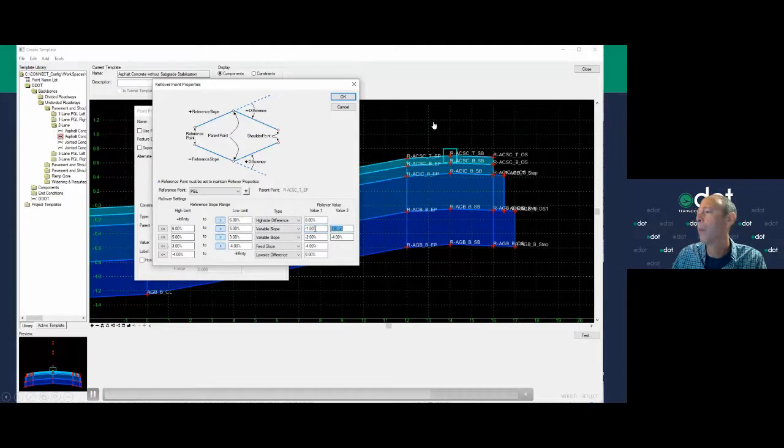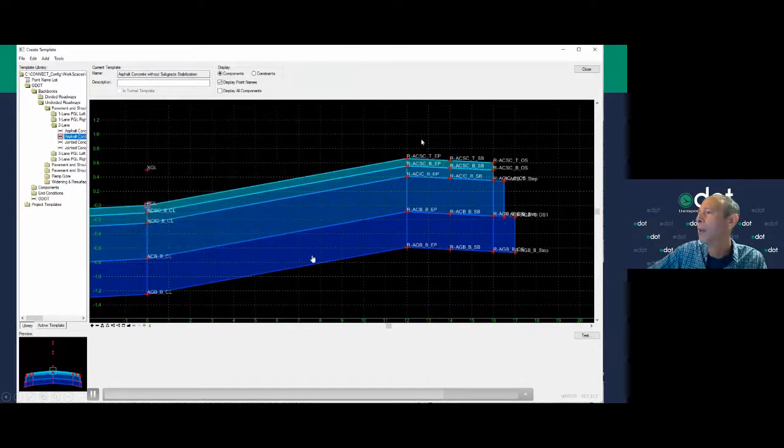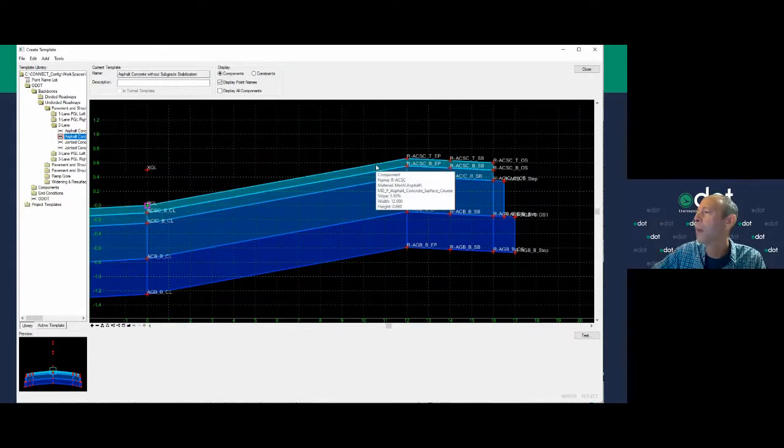So going back to edit the point, this is the value you want to change. If your super elevation rate is between 5 and 6, if you set that to -1, so 6% would be -1, and then 5%. And you can see as soon as I applied that, that did drop down. So I'm at 5.5, and over here I'm at -1.5.